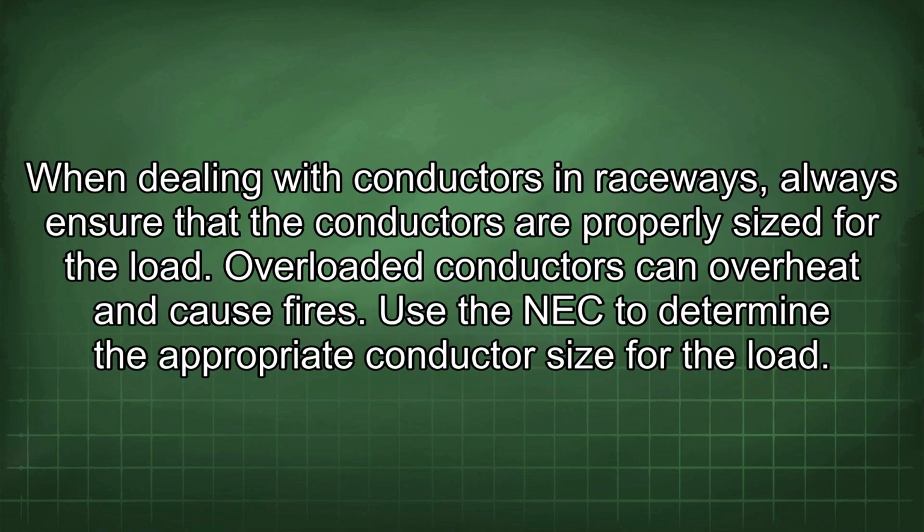When dealing with conductors and raceways, always ensure that the conductors are properly sized for the load. Overloaded conductors can overheat and cause fires. Use the NEC to determine the appropriate conductor size for the load.